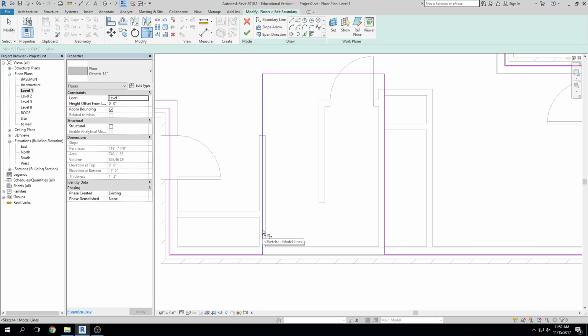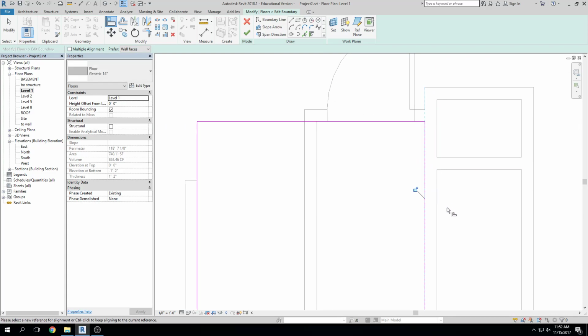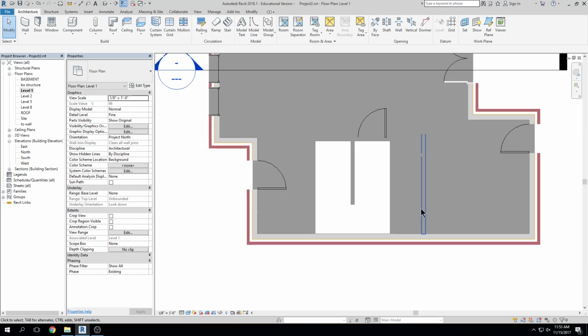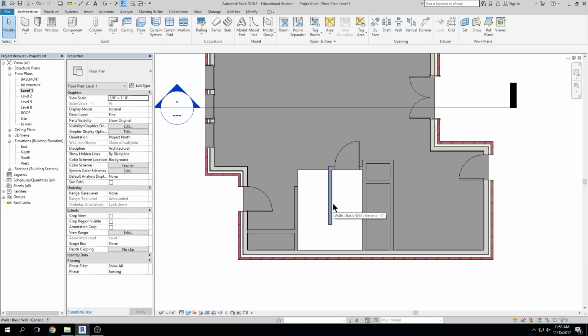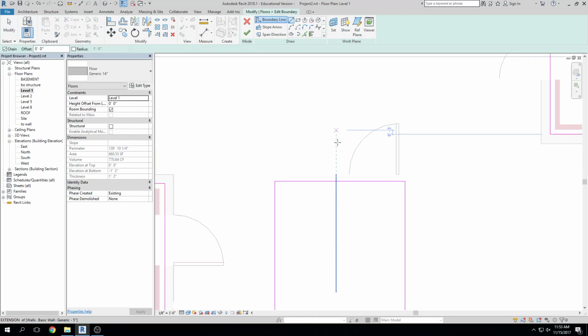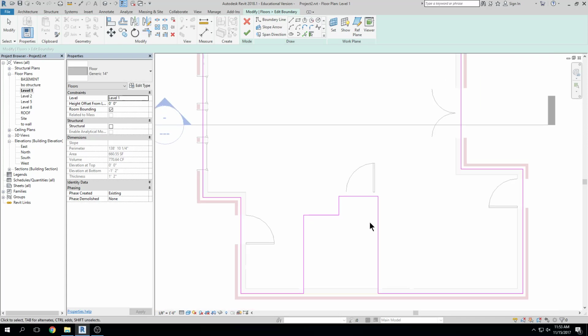Oh, sorry. Okay. So I've got my opening, and well, I guess while I'm here, maybe I'll just adjust it a little better. There we go. Okay, so there's my stair opening, and I hit finish. If I shade, SD, shade, there's my opening, right? So, looks pretty good, right? The opening goes around the wall in the center, although I think the stairs actually start back here, so maybe I need to hit edit again. And I need to bring this somewhat over here. There we go.